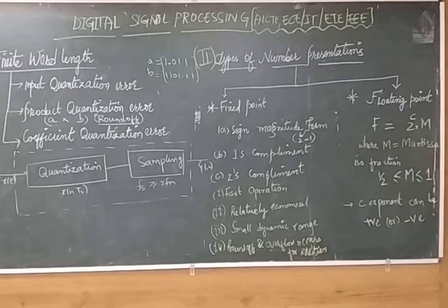If they are quantized, the frequency response of the resulting filter may differ from the desired response, and sometimes the filter may fail to meet the desired specifications. If the poles of the desired filter are close to the unit circle, the quantized poles may lie outside the circle, leading to instability.